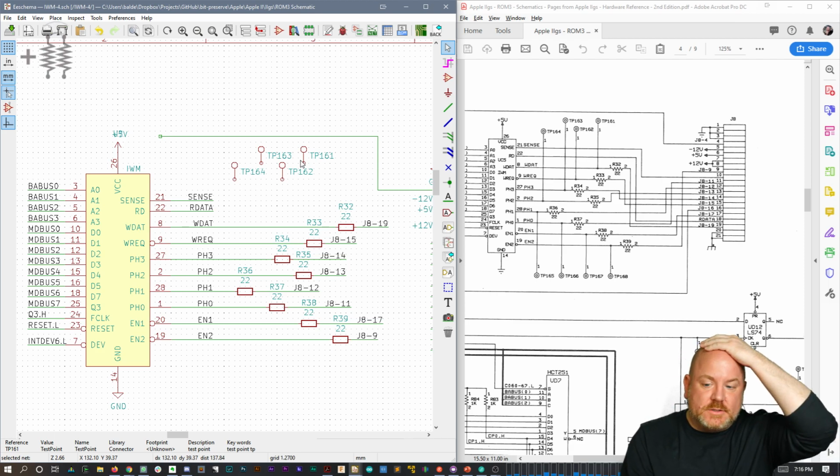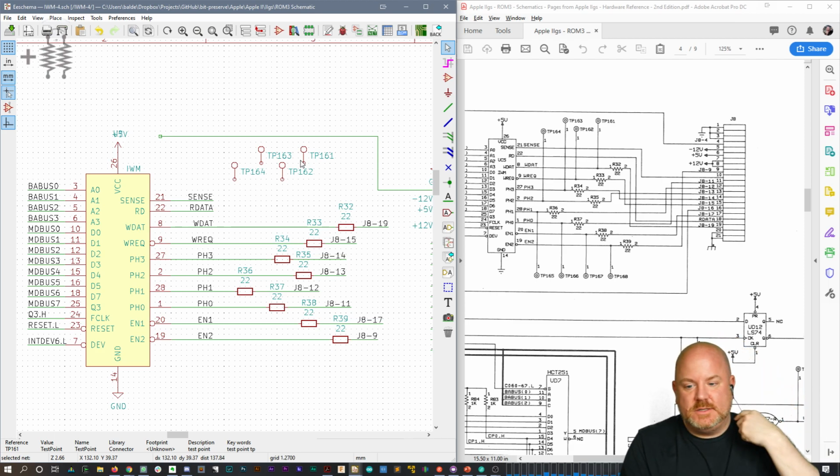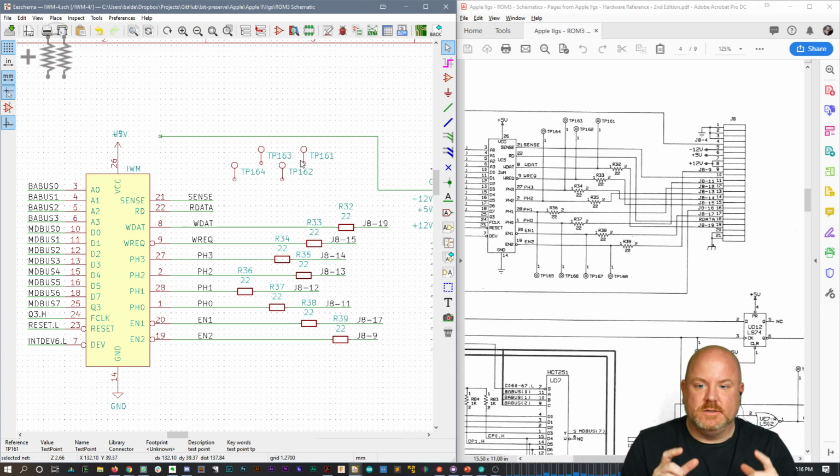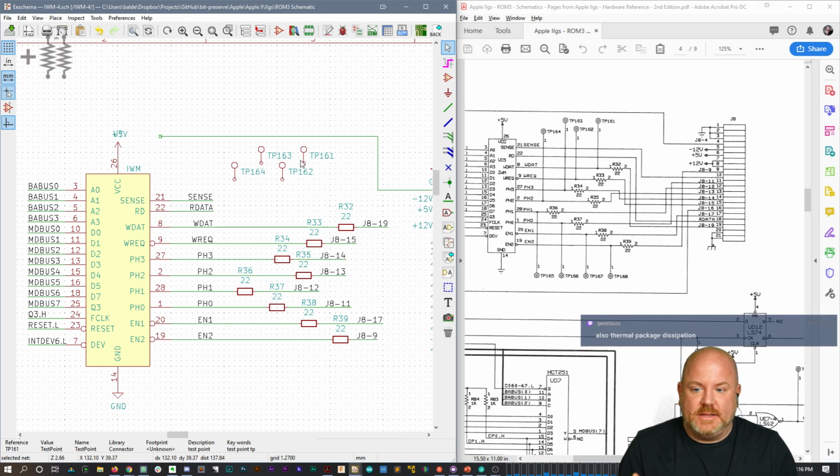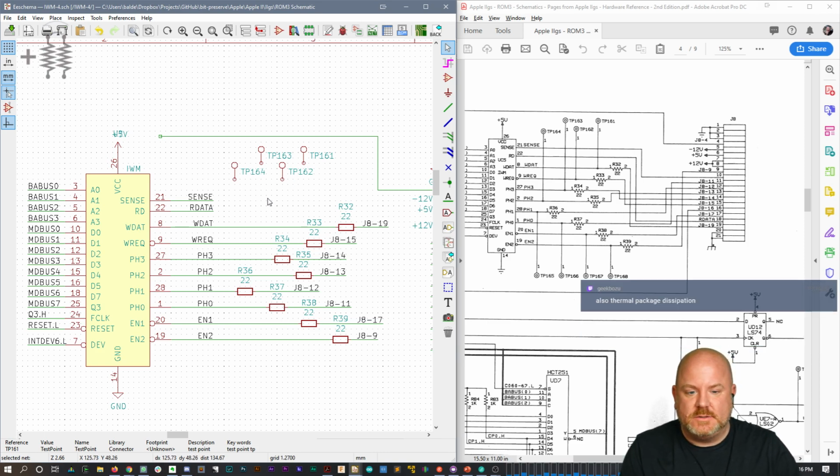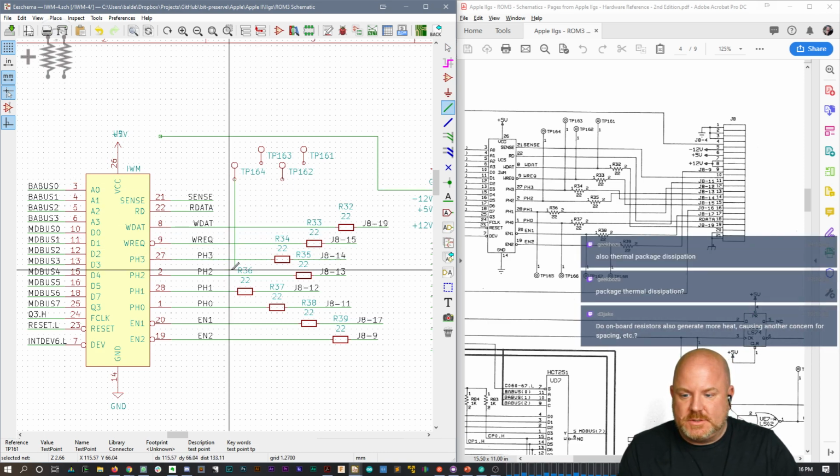When you go back to the 80s, when this stuff was being built, they simply did not have the space on the silicon to put a resistor. Instead, they would rather save the space for transistors. Also, resistors created heat, and as Geek Boy just said, you're dealing with more heat to dissipate, so it just doesn't make as much sense.